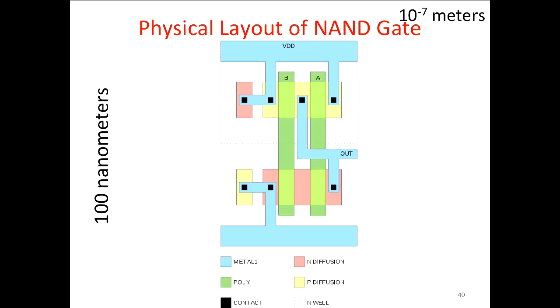And this blue stuff represents metal. So this is, these days, this would be copper, a copper trace. And these black dots represent connections down to the level below. So like what we call vias, where you go from one layer down. So the chips have multiple layers of stuff. Some of those layers are metal above the surface of the chip. And in the surface of the chip are the actual transistors. So the metal layers are used to wire everything together. And these days, like we mentioned in class, some of the chips have up to 17 levels of metal wiring to connect things together. We're only showing one level of metal here, this level at the bottom. You can see here, VDD, this is the power line coming in and actually touching the transistor here.